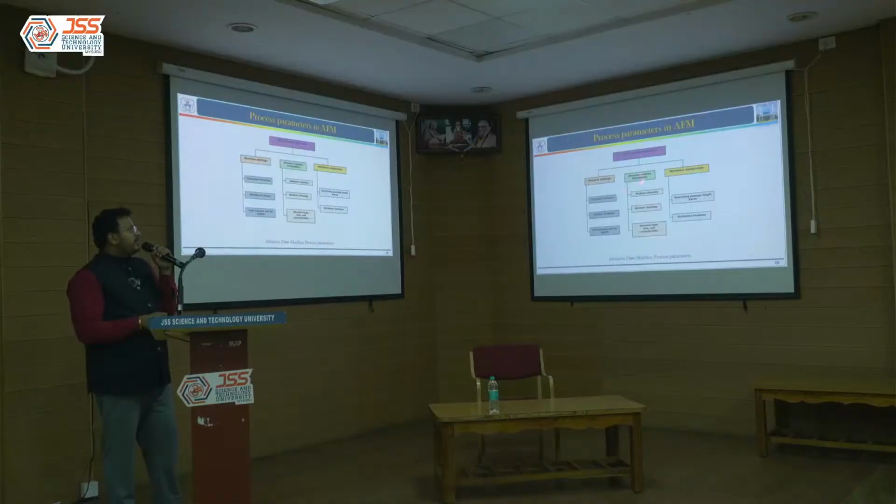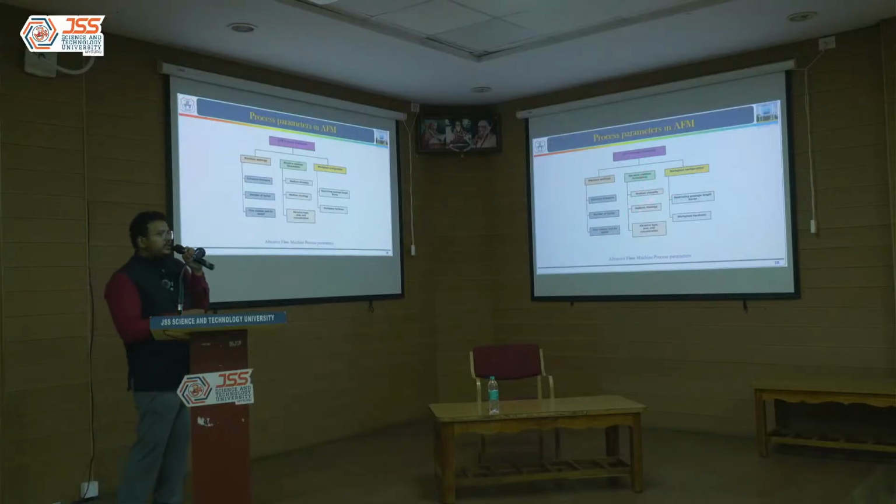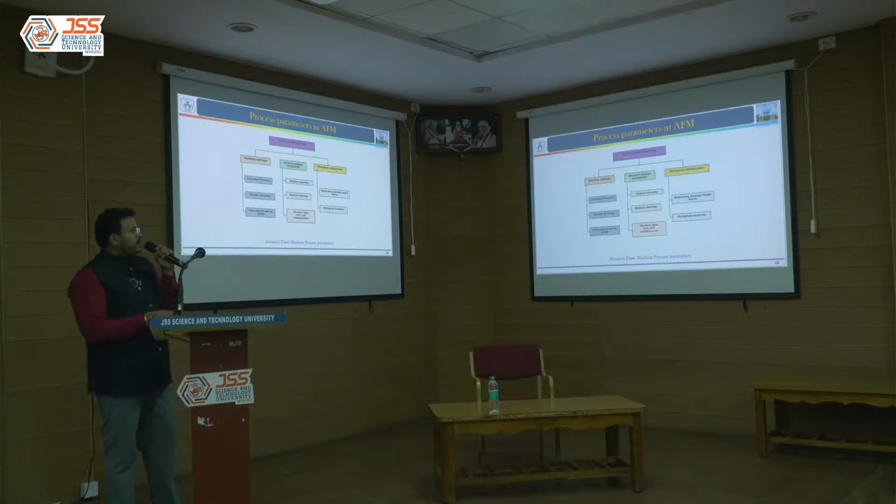Yeah. So the major parameters in this particular process are extrusion pressure, number of cycles, flow volume and its speed. Coming to media-related parameters, we have media viscosity, rheology, abrasive type, size and concentration. Workpiece configuration like restricting passage length and area, workpiece hardness, etc.